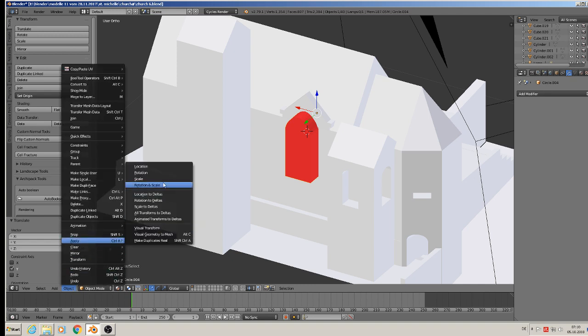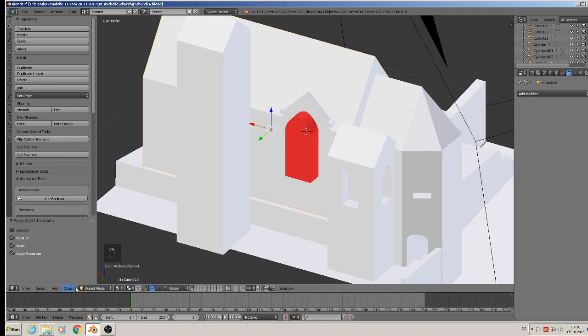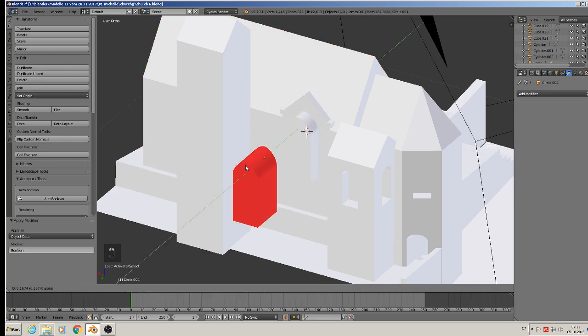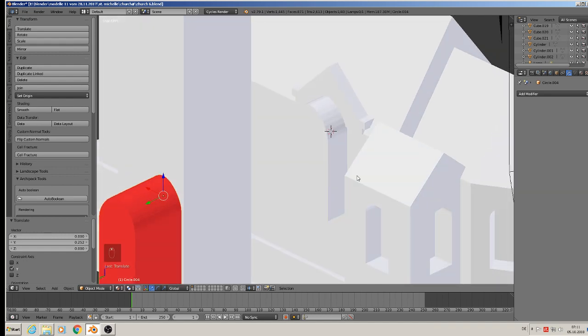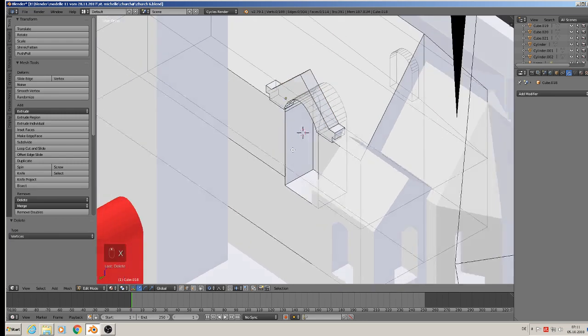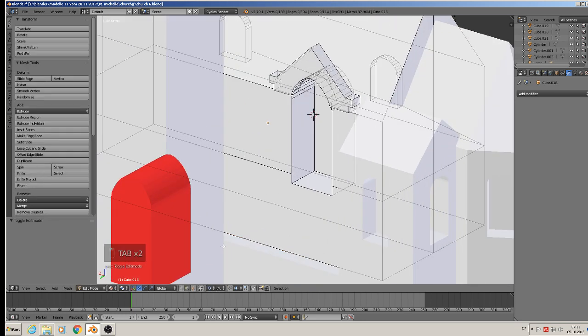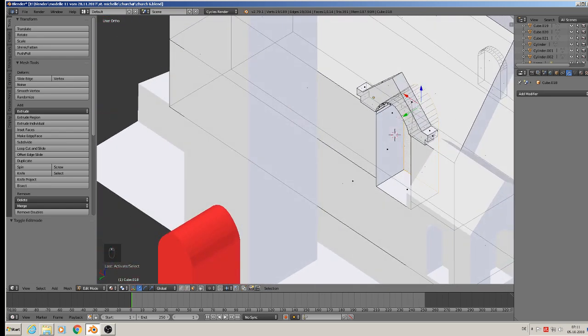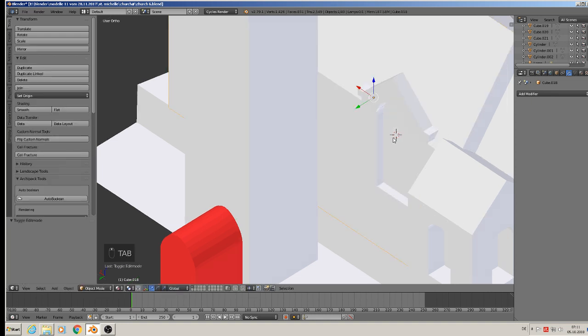We apply the rotation scale of that cutting object, then we apply this main house type. Then we have circle 4, the name, so we go here to the boolean, circle 4, difference, apply. And now, wow, we have an outer rim. Okay, so we delete the front, then it should be open, and it is open. Not bad. I didn't think that Blender makes that correctly, because I often try such and sometimes it doesn't work.